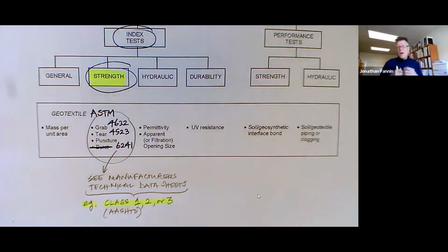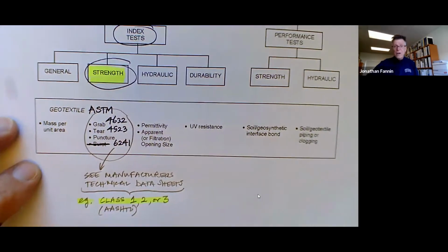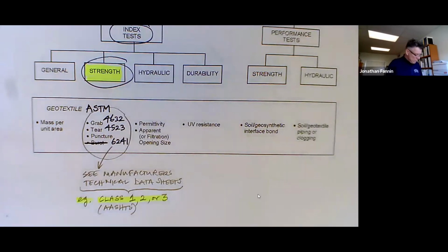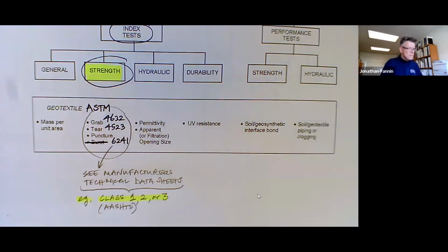The next thing, and now we get into the classic world of filter design. Arguably, if it was a granular filter, we want the material to be strong. We don't want it to crush. We don't want to be placing a granular filter where the soil itself, the sand, for example, is insufficiently strong because of its mineralogy or because of its grain shape, or that it's susceptible to crushing, for example. So that might be our mirror in filter design.